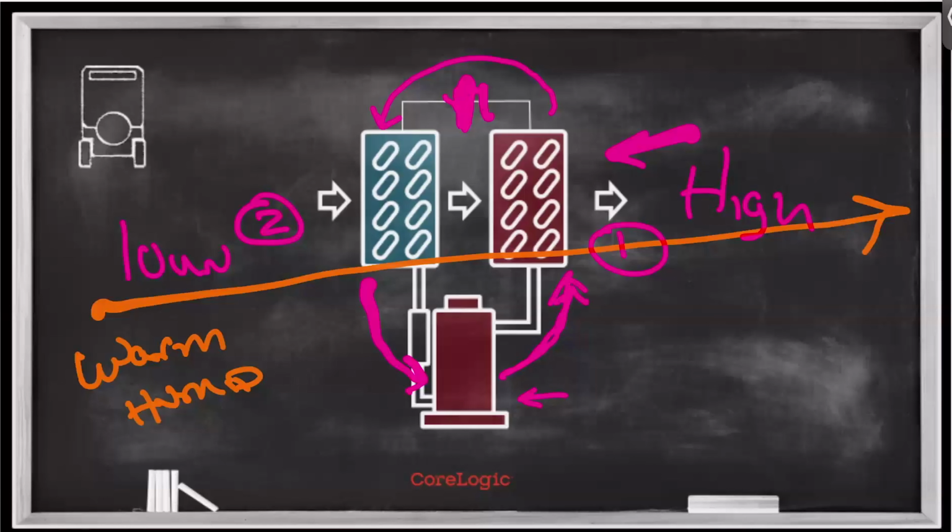Okay. So on the first coil, what's happening is we're taking the temperature of that air and cooling that air down to what we call its dew point. Dew point is basically how much energy is required in air to support the amount of moisture in it, right? So if I have air that's 70 degrees and it has a dew point of 50, that means that if I cool that air down to below 50 degrees, it can no longer support the moisture it has. That excess moisture is going to literally sweat out onto that surface. And the more I drop below dew point, the more sweating I'm going to get on that surface, right?